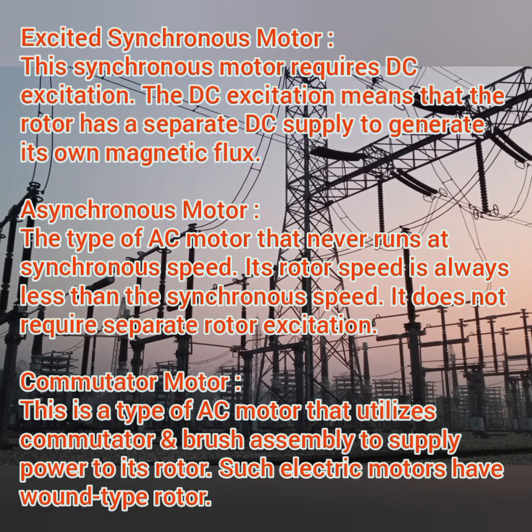Then asynchronous motor. This is a type of AC motor that never runs at a synchronous speed. The rotor always rotates at less than the synchronous speed, and it does not require any separate rotor excitation. So it works like a normal synchronous motor, but the synchronous speed will not be attained by your rotor.